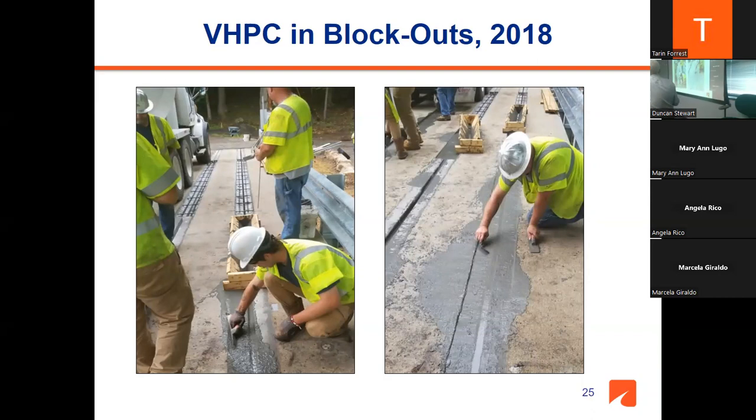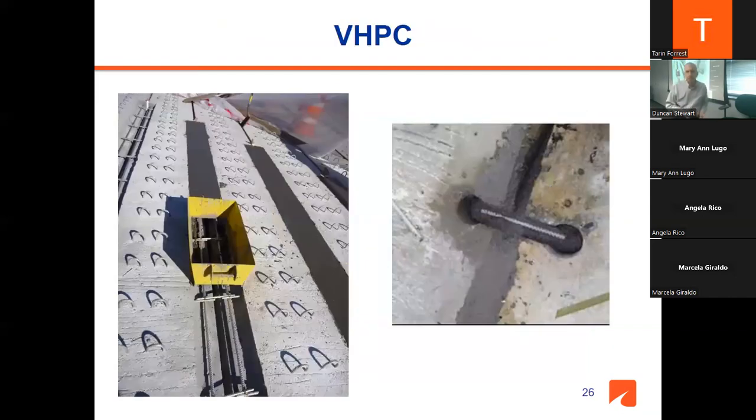Because in the old days, when we had 5 or 6 of them next to each other, we used post tensioning to hold them together. But we found that it doesn't work. It leaks. So now we are doing what we call a Virginia adjacent member connection, VAMC. Okay, so that's what he's doing. Now he's putting our concrete in there.